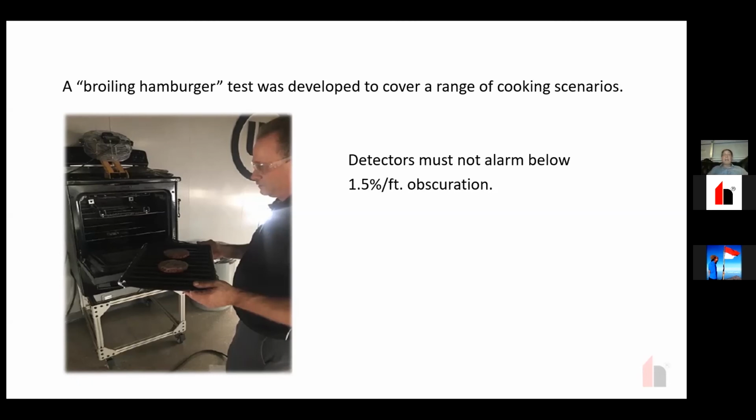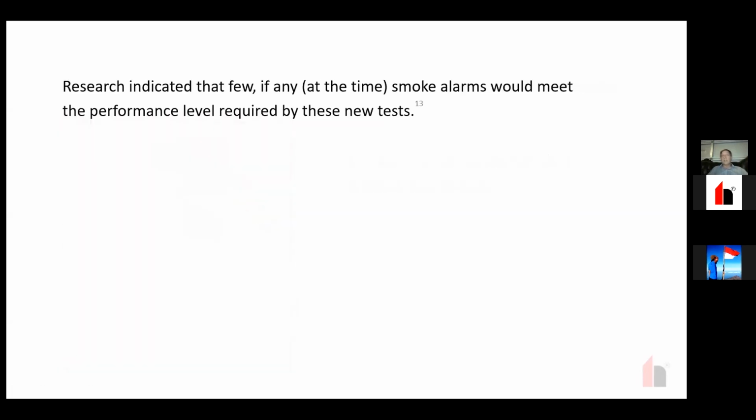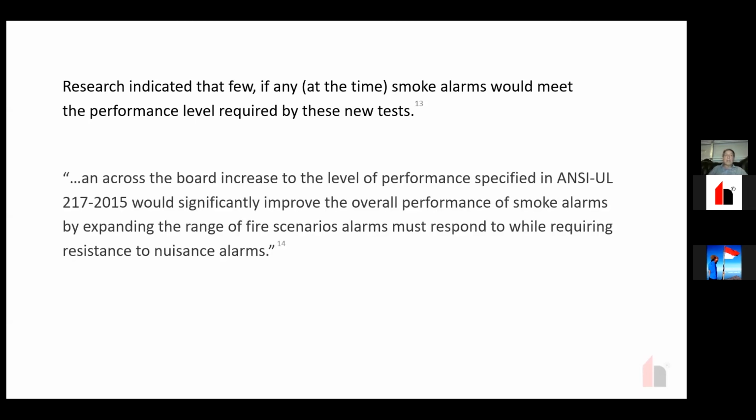So at the time, with the detectors that were available when these tests were established, research indicated that very few, if any, of the smoke detectors would be able to pass those tests, the PU foam and the broiling hamburger test. And yet at the same time, studies recognized that an across-the-board increase to the level of performance specified in these UL standards would significantly improve the overall performance of smoke alarms by expanding the range of fire scenarios alarms must respond to while requiring resistance to nuisance alarms.